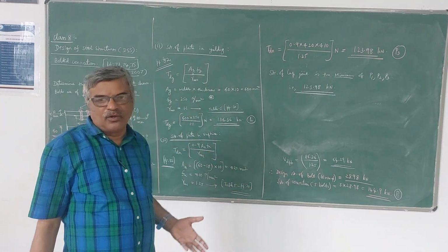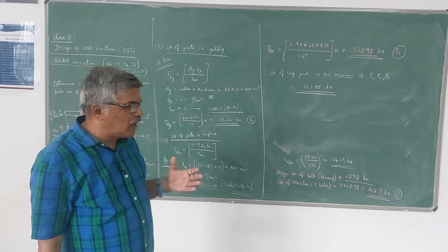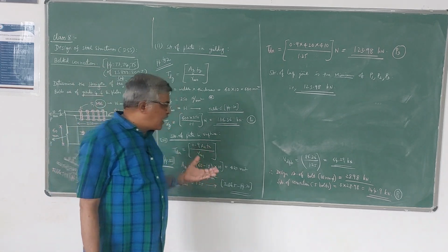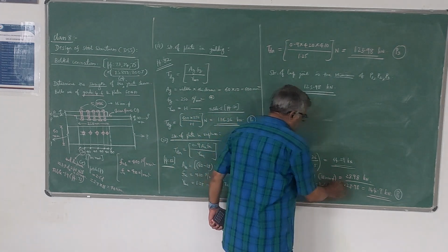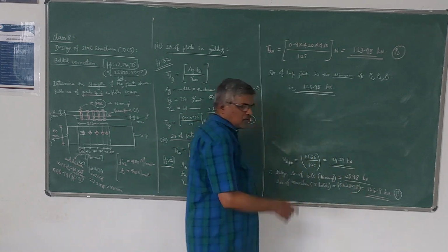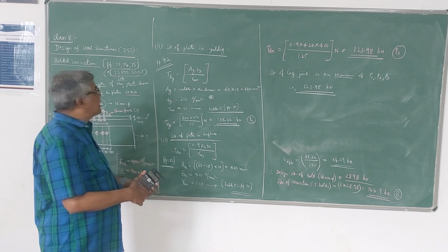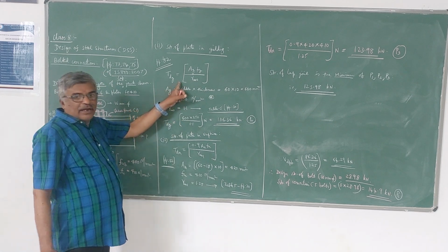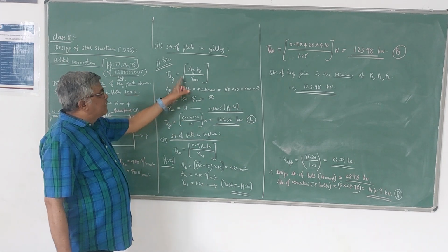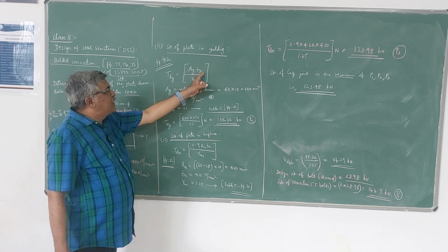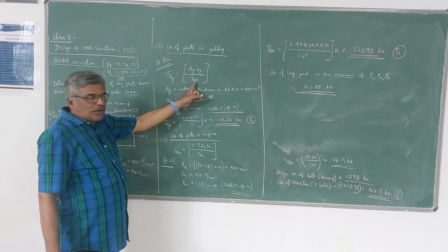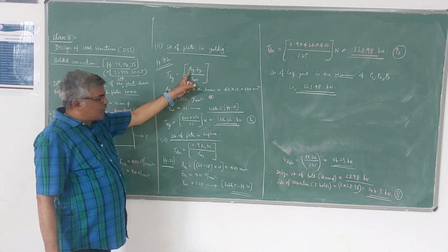Take the least value as the bolt value or the design strength of bolt and multiply that value by the number of bolts to get the strength of the bolts. So that is one criteria. Second criteria is strength of plate. You have to calculate one by yielding. When you are taking yielding criteria, you have to take Ag and Fy divided by gamma m0. So Ag is equal to thickness of the plate times width.